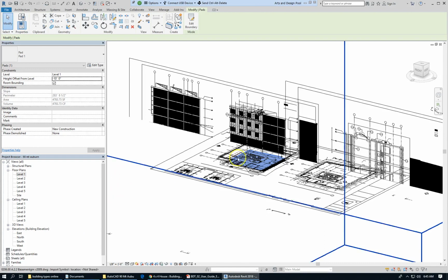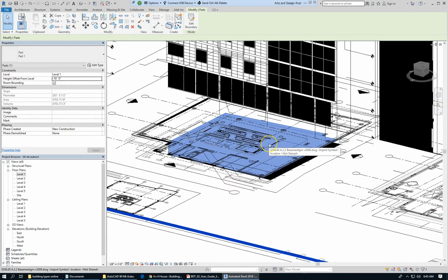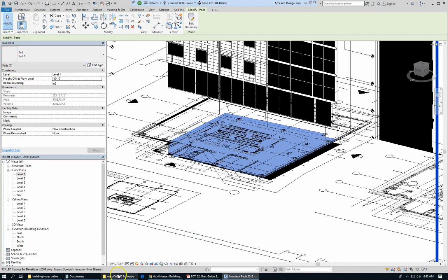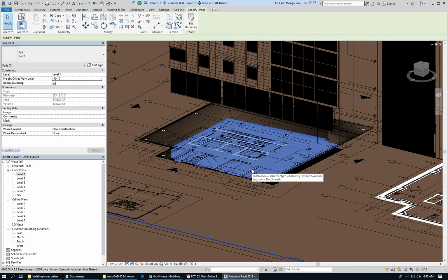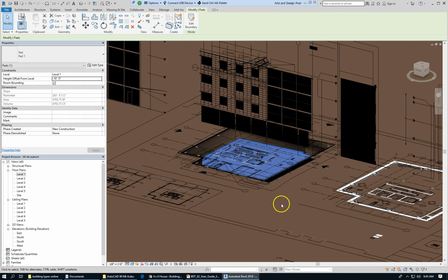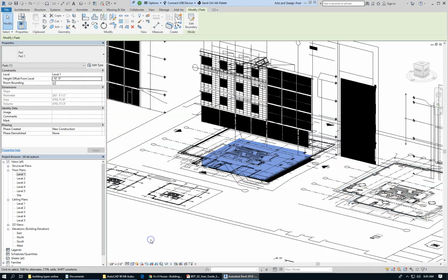This is step 4. I'm going to go in and make some refinements here. Remember, we drew a building pad. We arbitrarily placed it 10 feet below grade at an elevation of -10. It's selected here. It's blue. If I were to turn on some kind of shaded mode, you'd see this depression in the earth that corresponds to that building pad insertion in topography. Let's go back to hidden line.